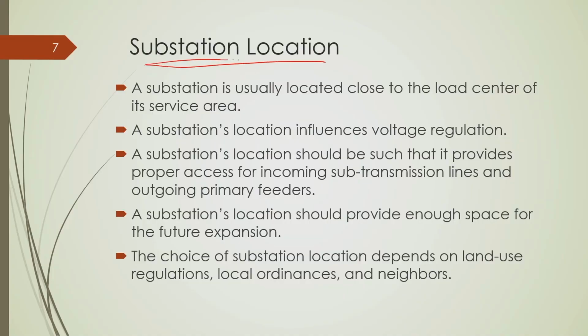Now, the question is, in order to design a primary distribution network, the first question is where do we place a substation, which is very important. So, substation location is an important factor. Usually, it is located close to the load center in a service area.